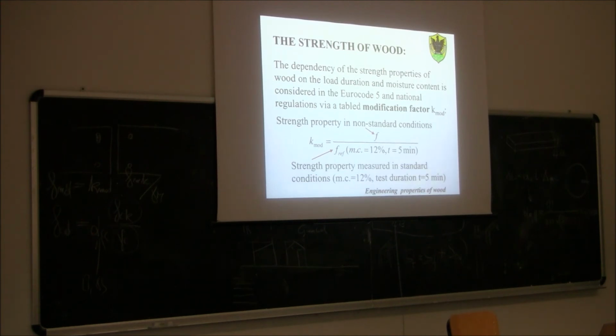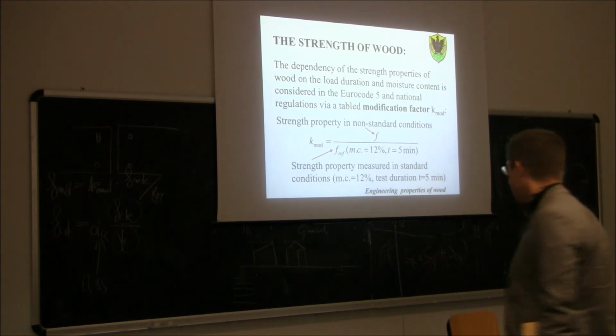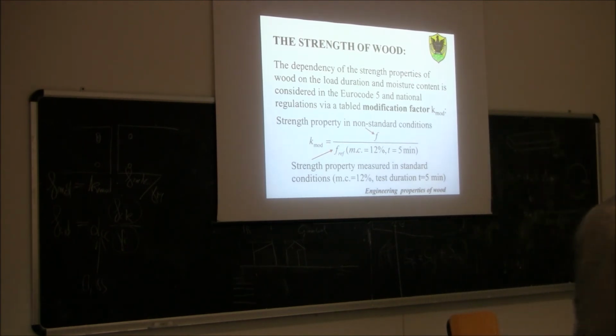Keep in mind that K mod is not a fixed value like 0.85 for concrete. K mod depends on load duration. We go down to 0.5, up to 1.1, and it also depends on moisture content. Clear? Okay.